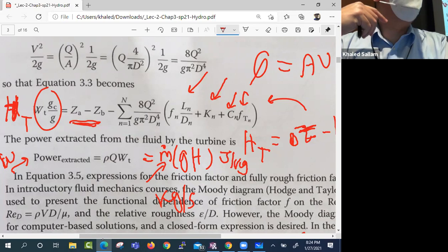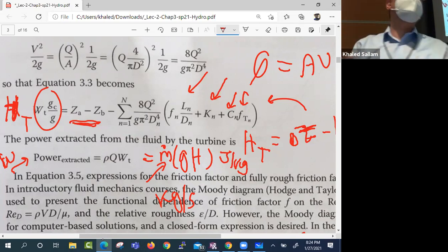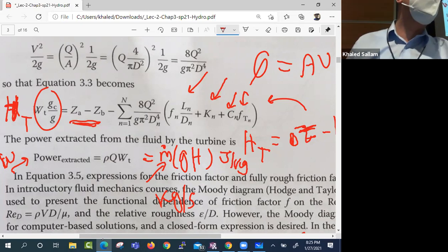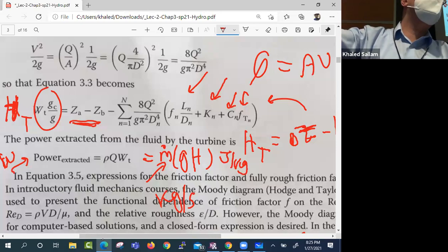So they are basically telling you our fitting doesn't always have the same K. It changes with the Reynolds number. So what's the best way to do this? Relate this to the friction factor. Like we are twice the friction factor. Find your Reynolds number, epsilon over d, whatever your friction factor is, our C is 2, multiplied by 2, or 0.5, or 0.1.